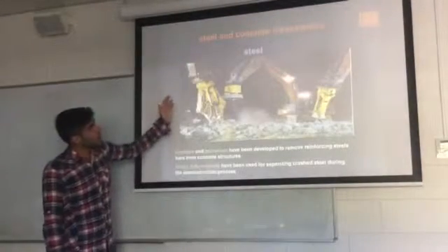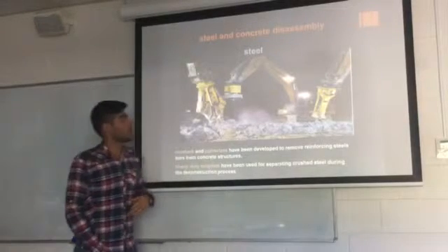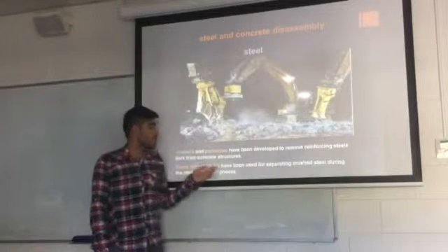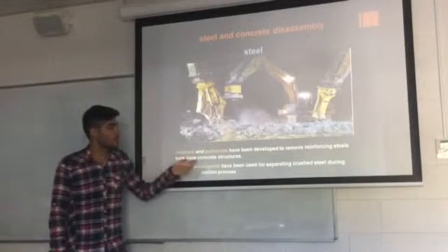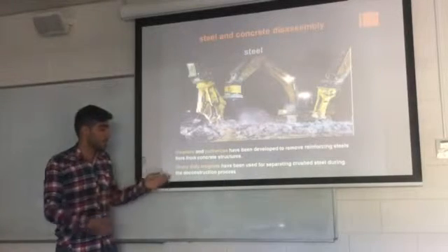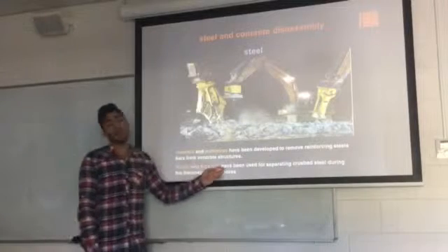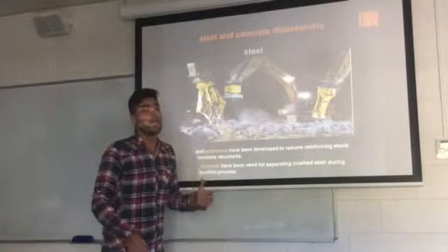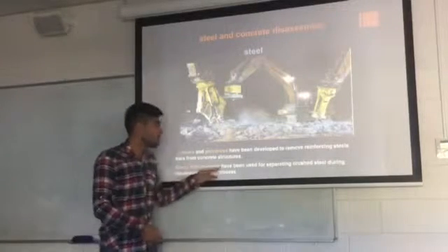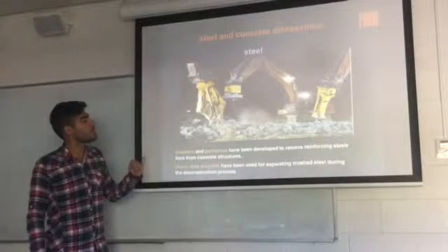The next slide is about concrete and steel disassembly. For steel disassembly, we need crushers and pulverizers to separate the reinforcing steel bar from the concrete structure, and we need heavy duty magnets to separate the steel from the concrete. It is a really useful method for steel disassembly.